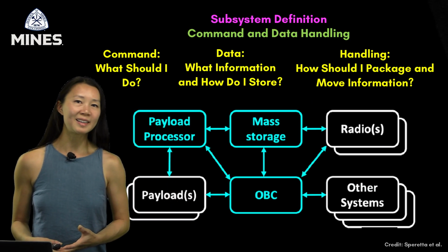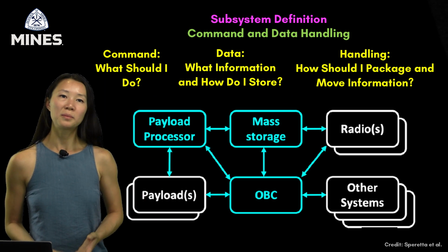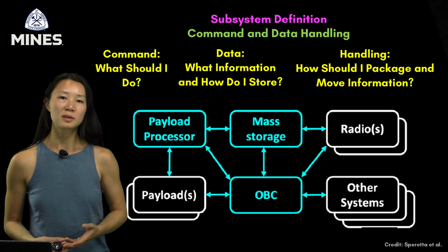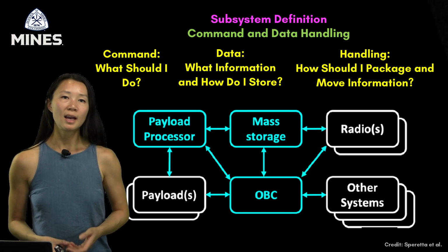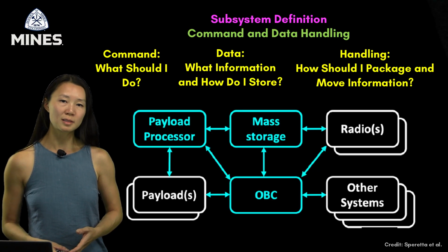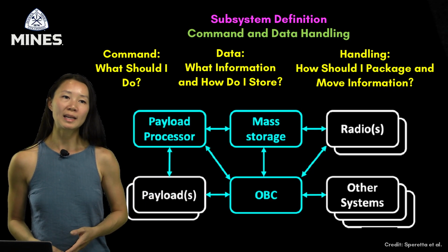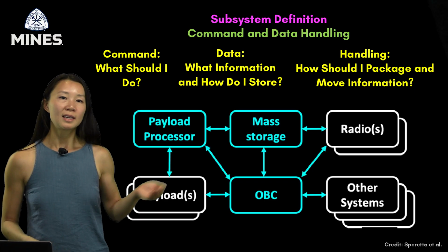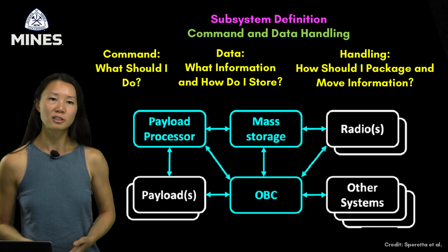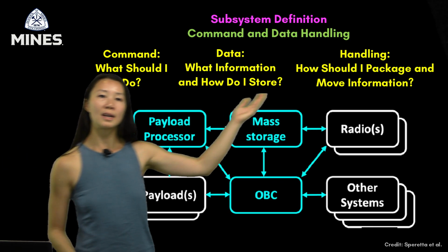All right, so to begin, CDH stands for Command and Data Handling. Let's define what we mean by Command and Data Handling, or CDH, which is often described as the nervous system of a spacecraft. At its core, the CDH subsystem is responsible for interfacing between all other subsystems, which you can see by all of these interconnected arrows, coordinating commands and data across payloads, sensors and actuators, and also enabling autonomy and supporting ground interaction. We can break this down into three essential terms: command, data, and handling.